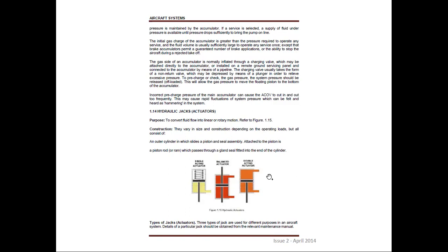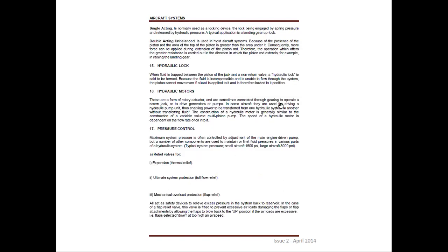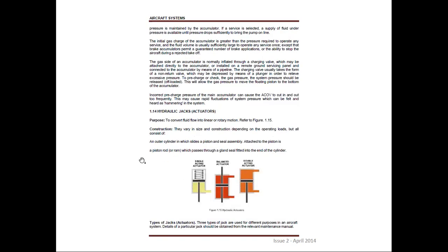Actually, the difference between a single acting and a double acting is the outlet port. The pressure is applied differently. Our single actuator only utilizes one outlet port. The balance actuators and the double acting actuators usually have two or more outlet ports. So that is the difference. Take note of this, because sometimes the difference between the two appears in quizzes.